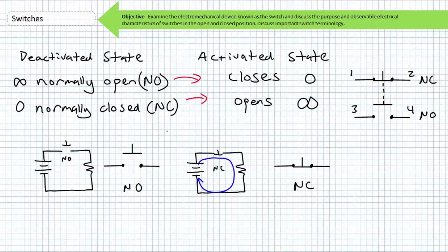For example, you would never try to simultaneously spin a motor clockwise and counterclockwise at the same time. Not only will it destroy the motor, it flat out doesn't make sense. And a mechanically interlocked package of a normally closed and normally open switch can be employed, as we'll learn in later lectures on motor controls, to prevent some dummy from doing so.